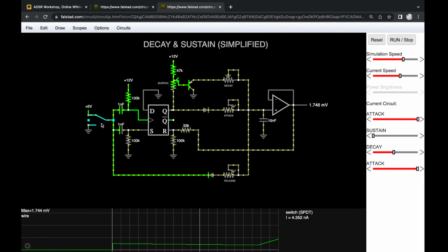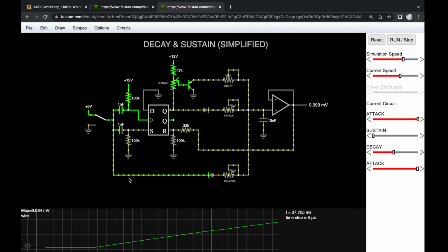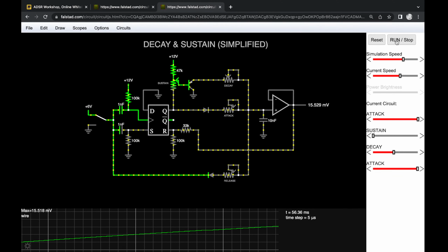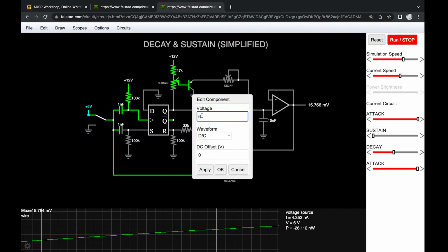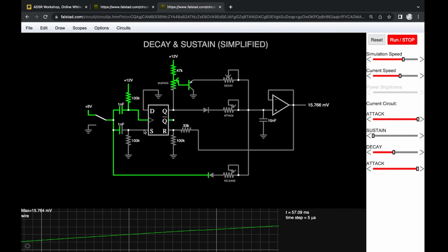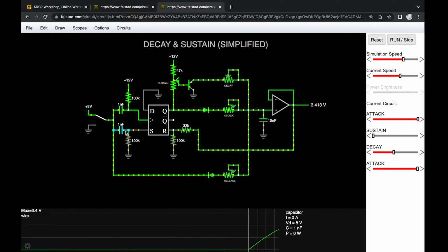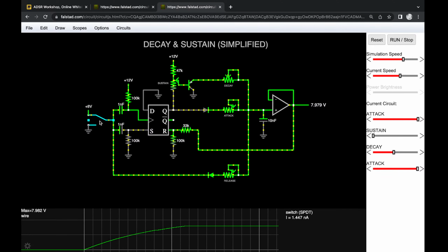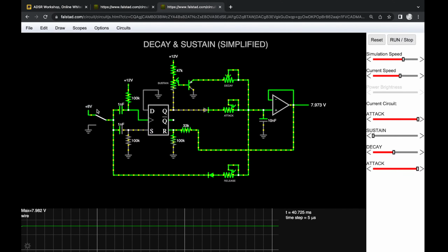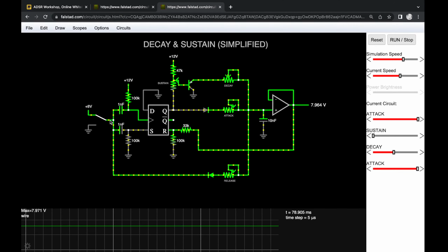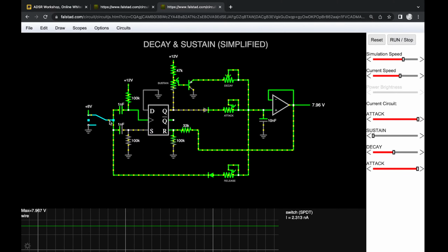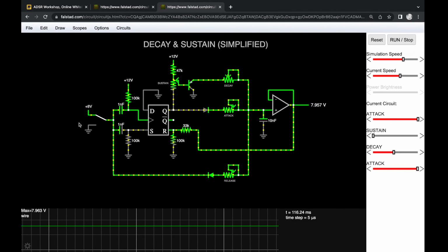So let's try this again. Boom. Oh, still 6 volts, it doesn't register. Interesting. So we probably have to go even a little bit higher to make this spike at over 6 volts. Let's try this. All right, so this worked. Now we're already at 8 volts, and we don't see the effect where the cap is discharging here.